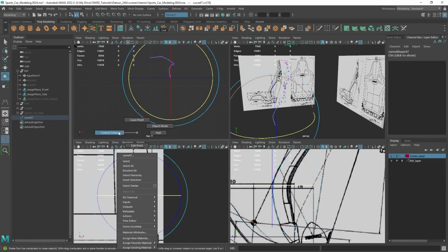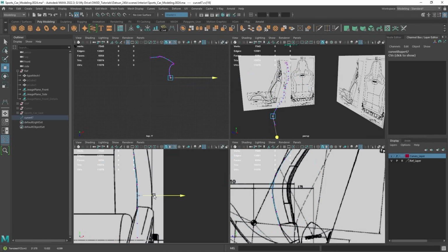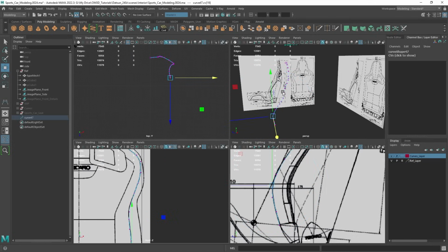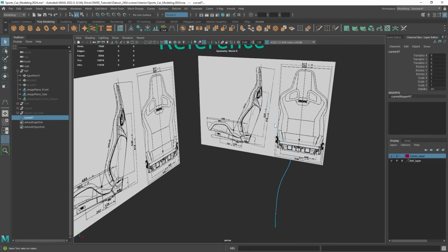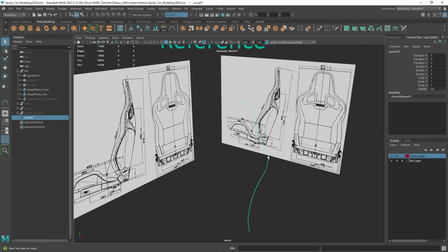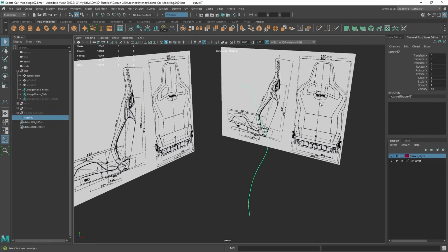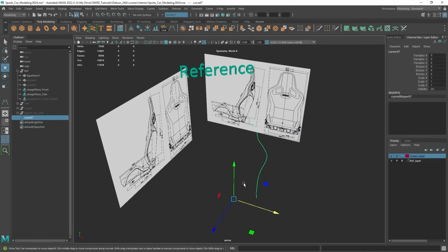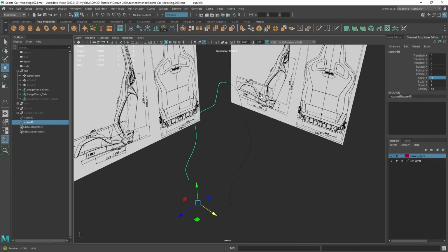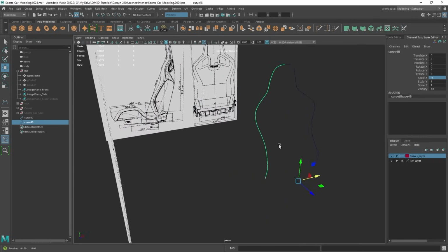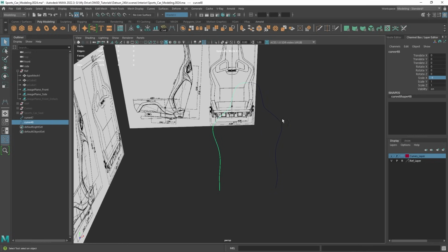You can just hold right click, go to control vertex and move it left or right like so. And this is what we got. So I use this process over and over again to do the entire model or the entire seat. So if I can simply duplicate this since we're on the line of symmetry here, Control D to duplicate. And we're using the x-axis as our line of symmetry, and you can just hit -1, and you can start to really build up these curves to create the main forms.